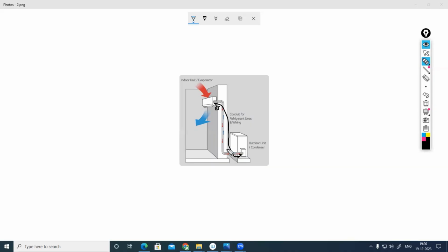But the problem is, if the manufacturer is recommending the socket outside but you have accidentally proposed it inside, then from inside to outside, if you want to provide the connection, we have to extend the cable. So cable extension, additional joint has to be done. That is not the proper way of installation. So that's why, with respect to the make, the power connection has to be provided either inside or outside. That is not constant. It will vary.